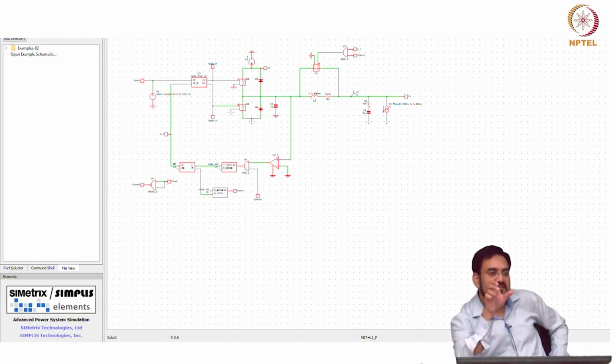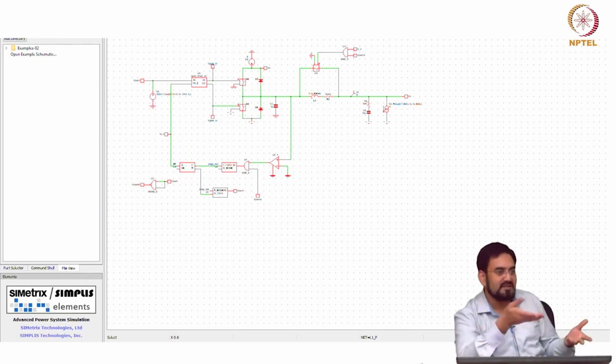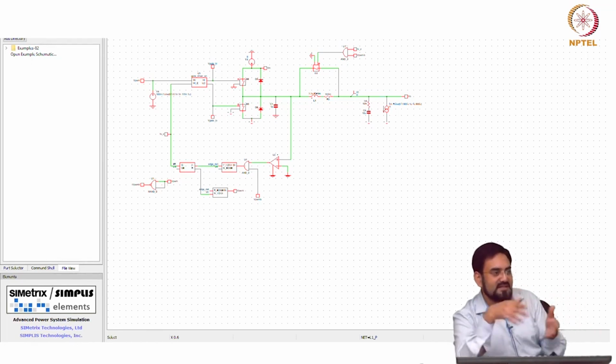What you are saying is, where is this energy coming from, but you are not exactly getting a 0. Even if you get it right at 0, this inductor has stored the current, just like a capacitor stores the voltage. The capacitor voltage cannot change instantaneously, and inductor current also cannot change instantaneously.